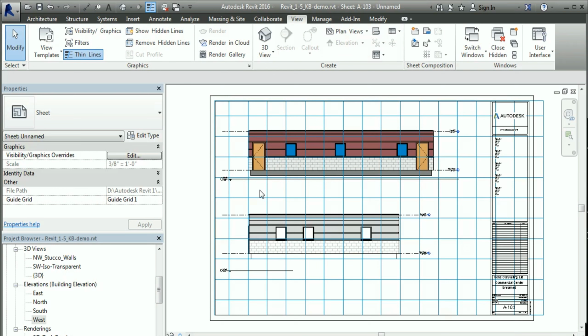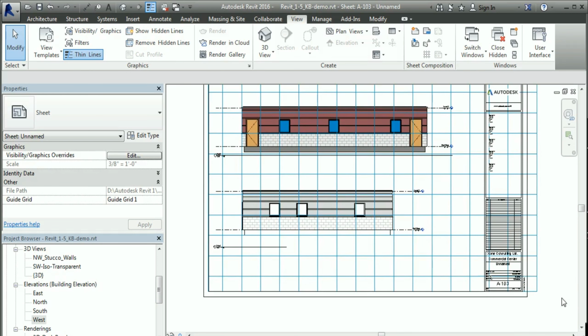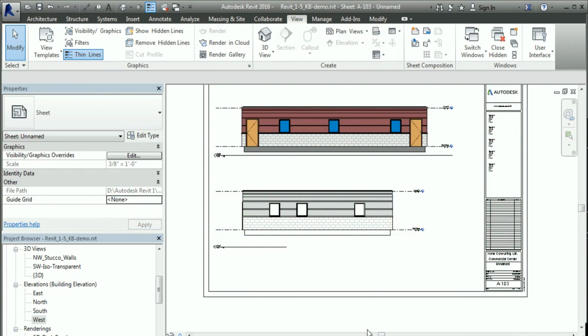in the same place. If you have a first floor, a second floor, and a third floor, all on different sheets, when you go from one sheet to the next, it's nice if the plan is actually in the same spot on each of the sheets. You can eyeball it and get it close, but these guide grids do certainly help to make it easier to align them perfectly. They won't plot. You can leave them visible. Personally, I prefer to use them, but then turn the display off after I have them set up.